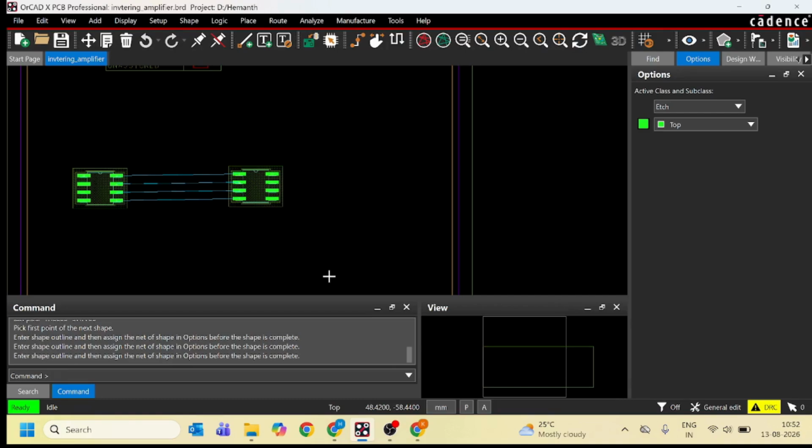As you all know, a plane means a cross-section chart. A cross-section defines the physical layer structure of our board. Before routing a multilayer board, it is important to define the correct layer stackup because it determines how the board is manufactured and also affects the electrical performance of high-speed signals.